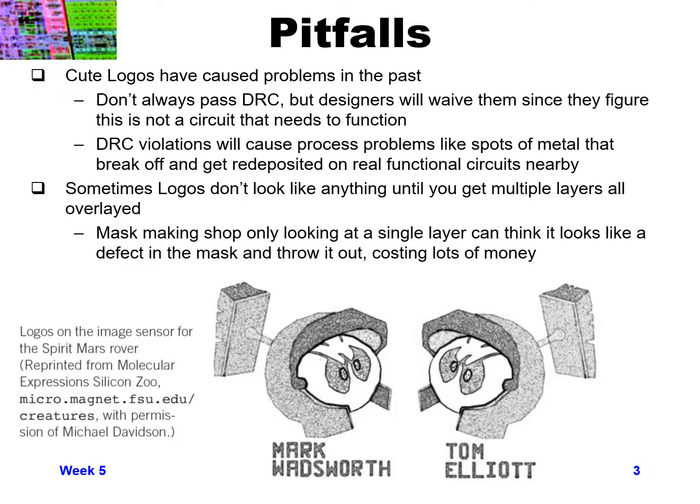So down below you can see a logo that was put on an image sensor in the past for the Mars rover. The thing to keep in mind is these cute logos don't always pass your DRC checks because you're obviously creating weird shapes and so on. But a lot of times the designers will say, oh, I'm just going to waive all those DRCs because it's not a circuit. It doesn't really need a function. But the problem is these DRC violations could actually cause some real process problems.